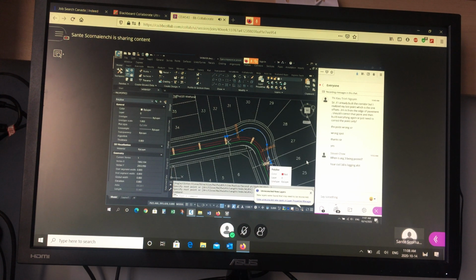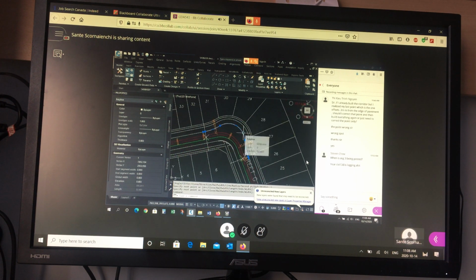So this is one way of ensuring that all the work you do is inside a space whose horizontal alignment is beyond the work you're going to do. This is always just good practice. It's a tip or a trick that I always use. Sometimes the alignment can start and end exactly where the widening start and end point is, and sometimes it doesn't. It depends on some of the settings in AutoCAD, and sometimes there are settings that you're not even aware of, so you have to be careful. I find it's good practice to make sure the alignment range includes the actual widening range. It's not at the limits, but beyond at the beginning and at the end.